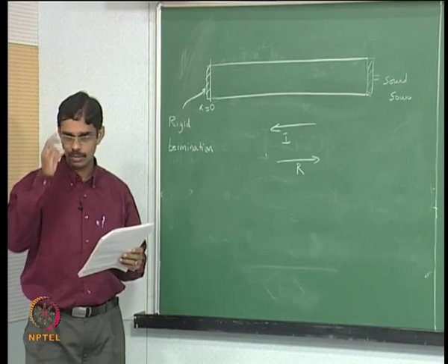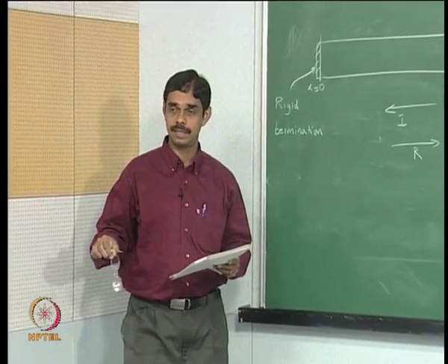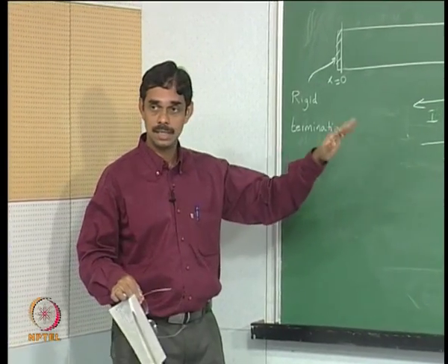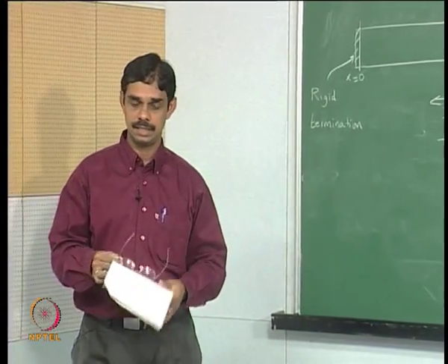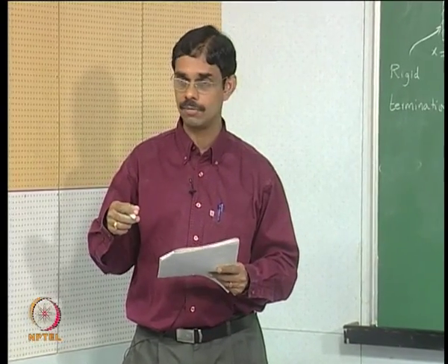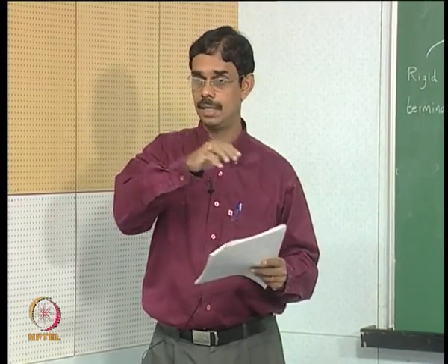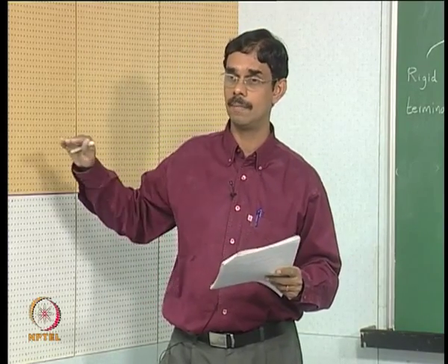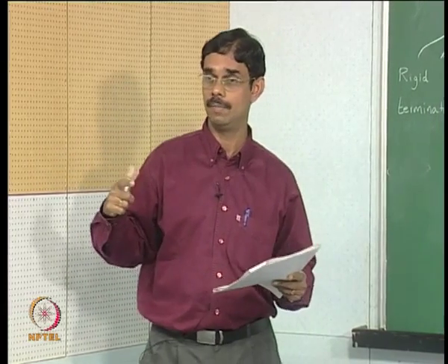We will not look at a complex omega, we will set up a real omega. That means there is a sound source and we have crossed the transients and we are reaching some kind of steady, stationary standing waves. So there will be no growth or decay of oscillation in time, which means omega can be chosen to be real, but we will look at the wave number, which can be complex. That means in the standing wave you will not have the same maxima for all the maxima; they can be growing or decaying, and that will count in terms of the wave number.